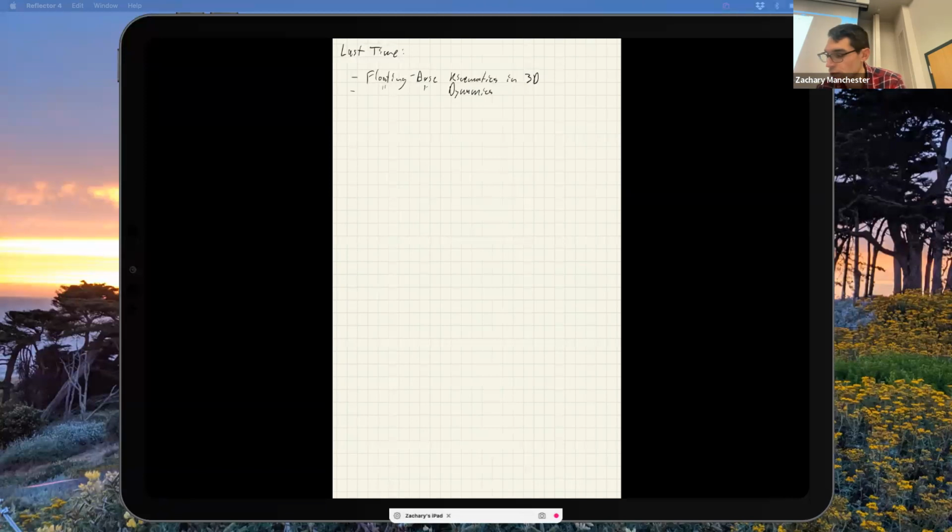And then we did the floating base 3D dynamics in 3D, right, in joint coordinates specifically, which is kind of the standard thing that pretty much everyone does, and that's most common in the robotic simulators. It's definitely most common in control, and arguably the most common thing in simulators. This is what Bullet, Dart, and MuJoCo all do, this setup, right?